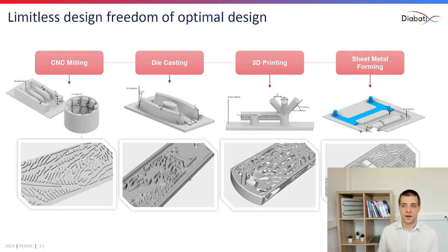Maximal channel width is, of course, very important to make sure that the pressure exerted by the fluid doesn't result in permanent deformation of the plate, as well as minimal and maximal structure width size. Minimal size, of course, being very important to glue or to weld the stamped plate to the top plate for structural reasons. And then some additional settings like deformation angle, fillet radii, etc., where you have full control over.